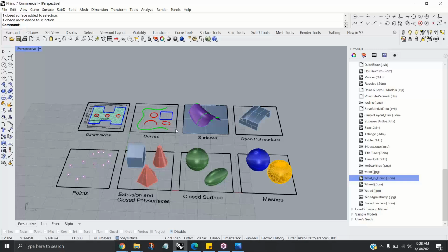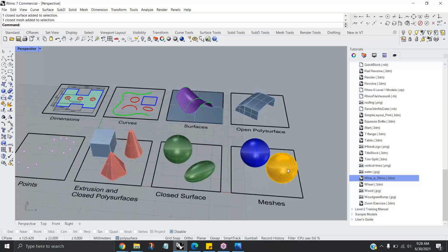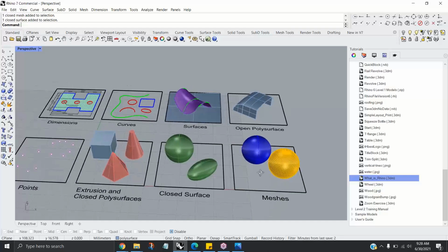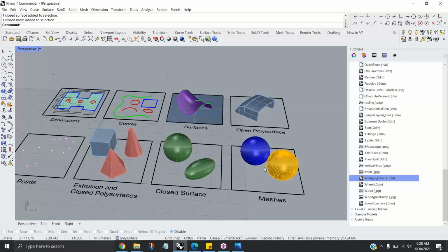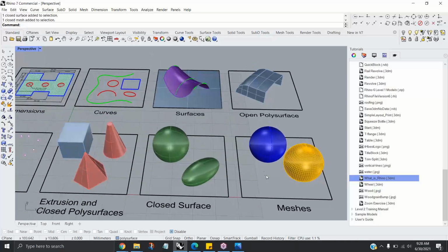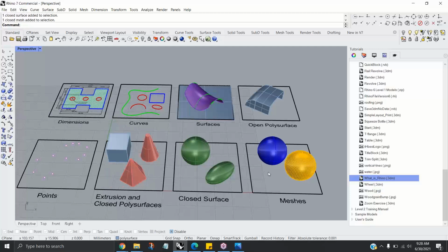So if you have 3D Studio files, or you go out to Google Warehouse and you get a sink or a shower for our guest house, then you can import those into Rhino. They are different. They don't have all the options and flexibility that Rhino surfaces have. They're a little bit more of a rock, but we're getting more and more options in the newer versions of Rhino. So if I need a sink from Kohler, I don't need to edit it. I just go out to Kohler and get a sink and bring it in.